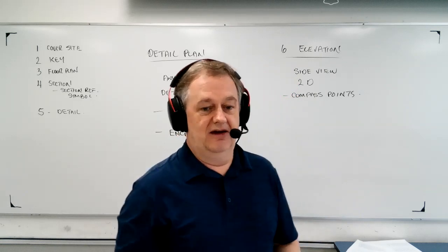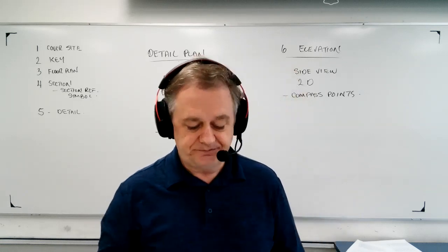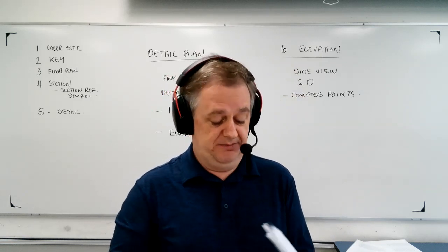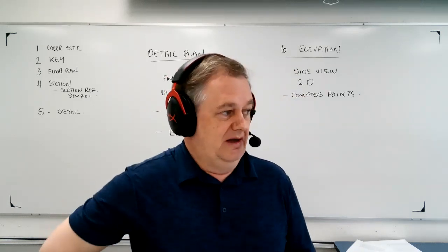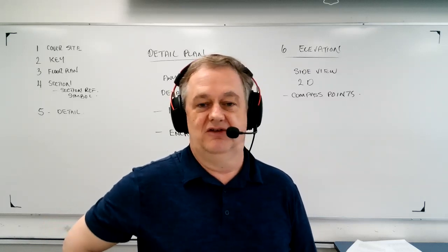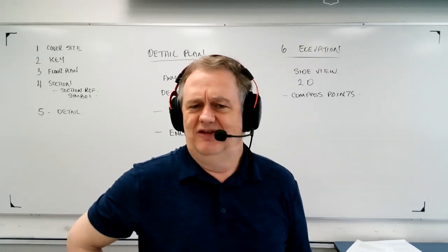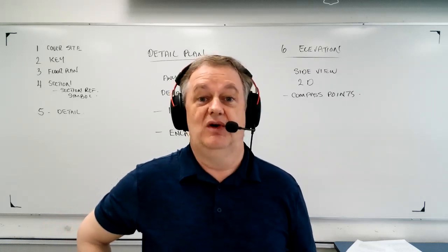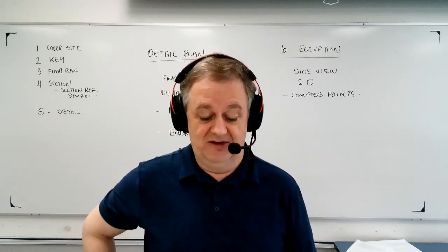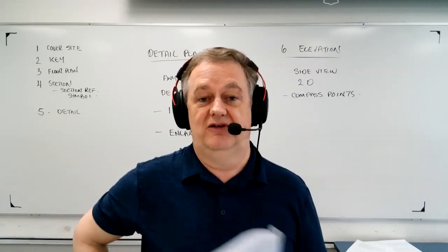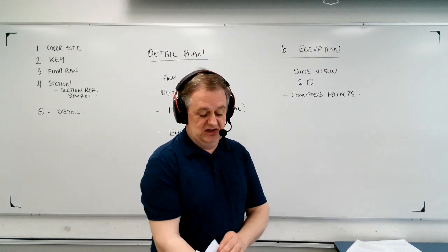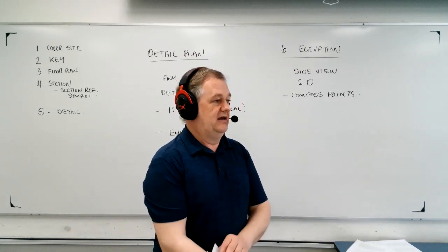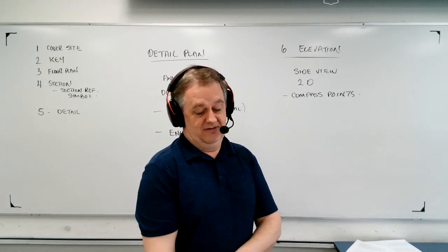And incidentally, in the electrical field, we definitely depend on this a lot, because if you go into a room and all you see is a big wall there, but you know what they're going to be putting in millwork here, and the plugs need to be 6 inches above the countertop. And how high is the countertop going to be? So you're going to be looking into a millworking set of drawings to see exactly where you have to box your outlets. So lots of information that can be gained, but then again, these interior elevations are quite often part of an architectural section, not even an electrical section.